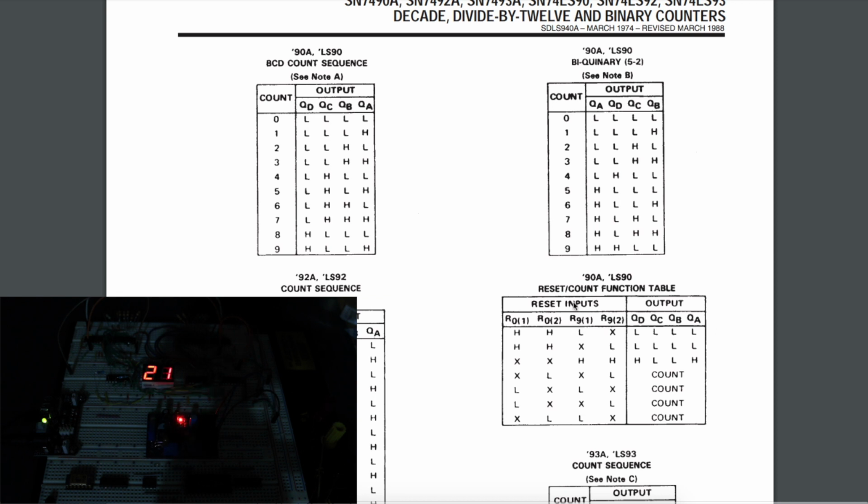This all starts to sound a bit confusing and convoluted. So usually, if this is just set up as a free-running counter, most circuits just take all of these reset inputs and set them all low, which is valid for just counting. But in my case, I need the ability to also go into a reset state where I can set all outputs low, so I need to study this a bit more.